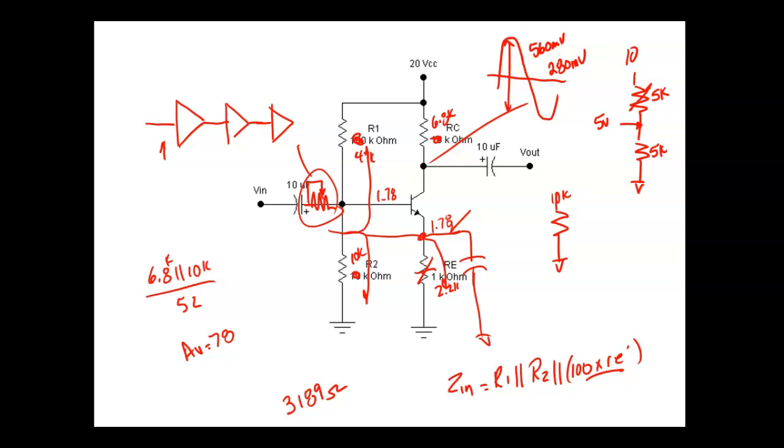So the 0.7 volt is gone out the window because there's no current flow. So if I was to come over here on a diode, like that, and I was to put 10 volts right there, and I don't hook this side up to anything, and I come over here and put my voltmeter right there, it's going to measure 10 volts. Because now it's not a forward-biased junction, it's just a piece of silicon in there that has no current flow to it. And that's what people have problems understanding. If you have no current flow through a device, then that device is not going to drop any voltage.